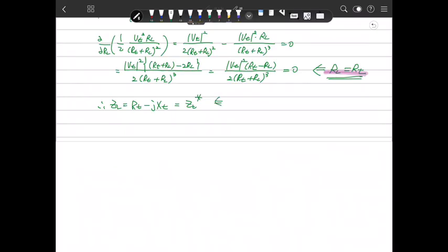If we define this load impedance given ZT and Vt, the load receives the maximum power from the voltage source. This is the maximum power transfer theorem. ZL should be the same as ZT's conjugate.